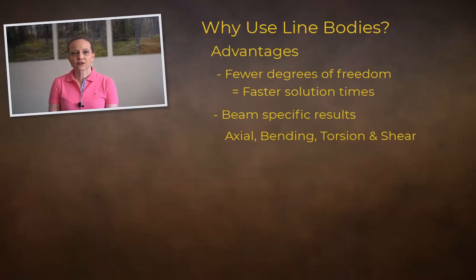In the case of slender structures, we are often interested in identifying and separating axial and bending behavior, for example, to determine how the slender structure is responding. This is directly possible with line bodies because its formulation incorporates these modes of deformation. On the other hand, this would be very difficult or tedious to attempt with a solid mesh, which is intended for more general modes of deformation.